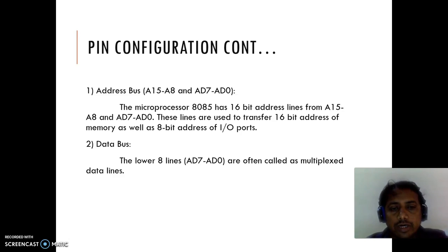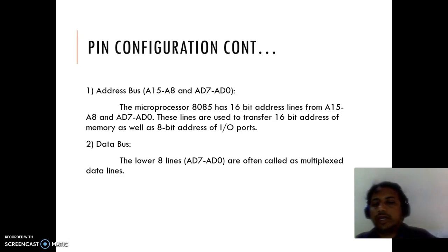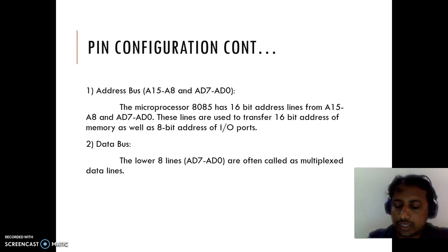One more important thing about this is the address and data lines. 8 pins are used in a multiplexed way, as both address and data. The next 8-bit address is dedicated to 8 other pins of your 8085.